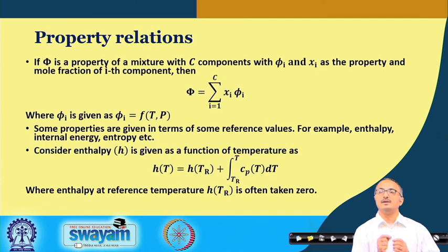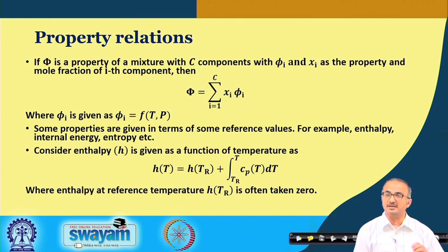So, whenever you are taking values from different sources, make sure that the reference temperatures are the same. If not, then you are going to commit a mistake, and whatever result you obtain will also be erroneous. So, that is the very important point one should note about the reference state.